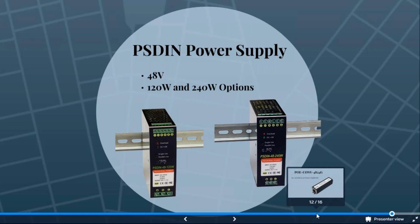All of our unmanaged switches will just provide PoE output. There's no way to turn off the power from that. If you're looking at mid-span, we do have some rack-mounted mid-span options, 12-port and 24-port. But if you're looking for a managed switch that only provides data on certain ports, yes, you can do that and turn off the power.